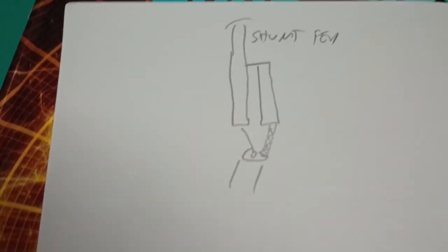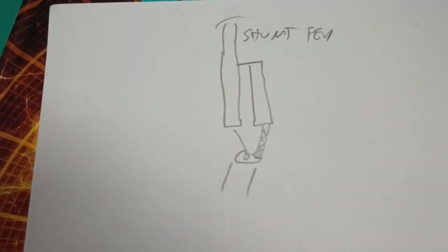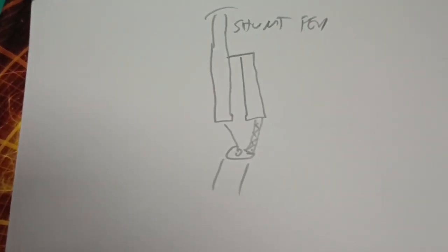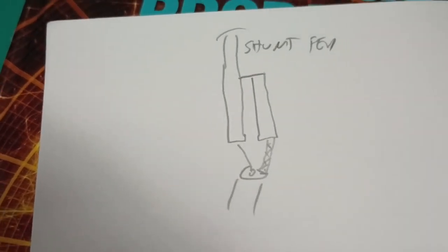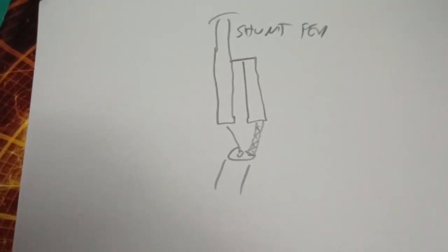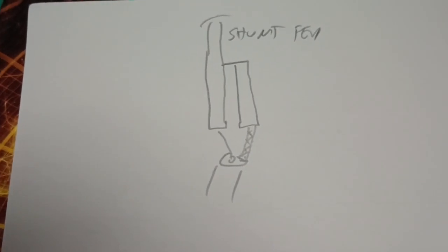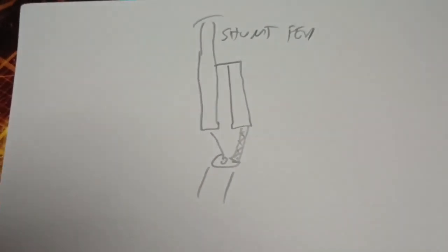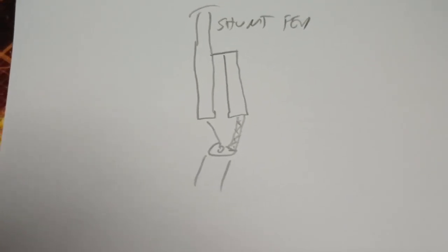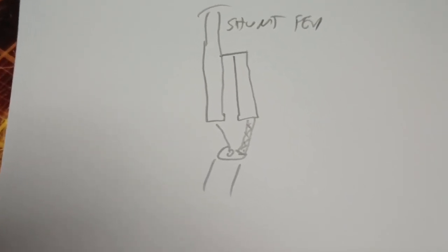It has to have something to couple into or it doesn't do squat. And this is why, when folks make the mistake of making loops, they have to put a giant high voltage capacitor at the feed point, because the energy isn't going anywhere and it makes high voltages. It destroyed the first few capacitors they tried to put on it, so they had to go to a bigger air variable and then bigger, because of the high voltage arcing.